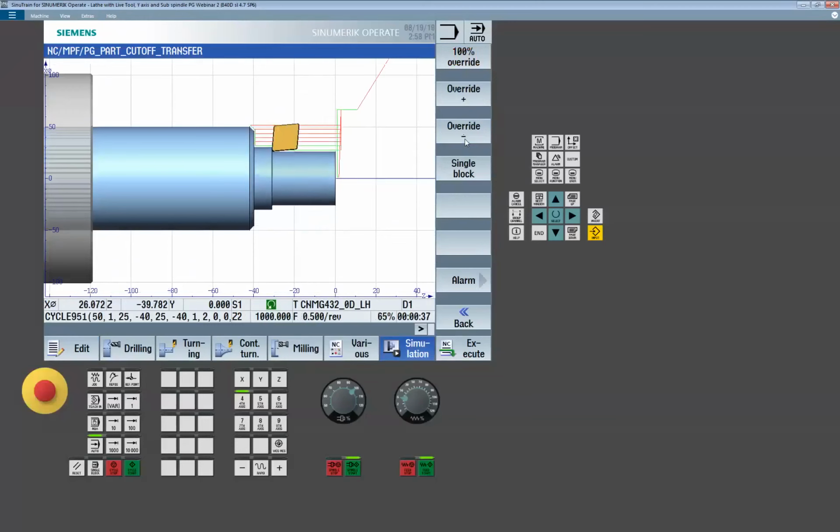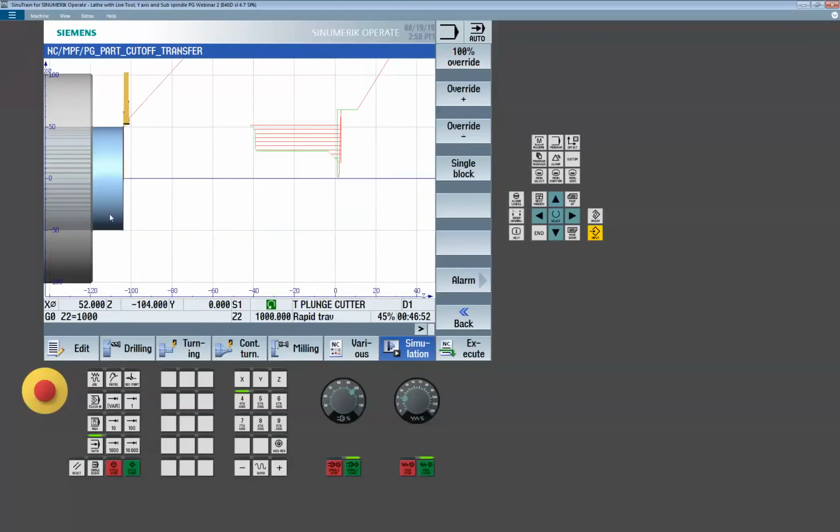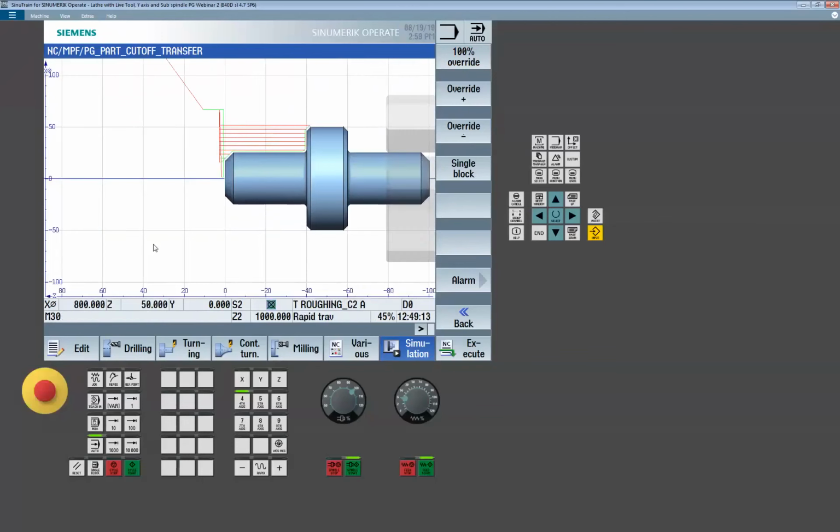So here we're cutting our part, and then we're going to come off and part it. So if you look at how much, we grabbed it, we're spinning. So I don't have enough material there to cut the next part. So I would have to add some kind of a bar feed scenario to get it out, or maybe a bar puller or whatever. But there would be another operation required if I wanted to come down and then machine the next part or the next piece in my production run.